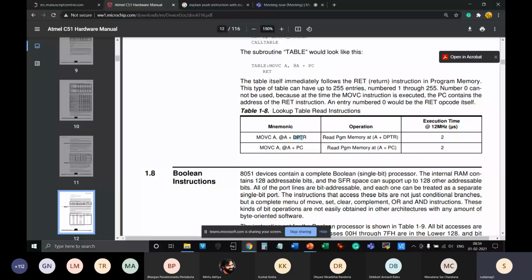Obviously your result should not overflow beyond 16-bit. Okay, that is another consideration here. The result of the addition of the DPTR value, a 16-bit value, plus the 8-bit value in the accumulator should not go beyond 16-bit. So the result of this addition must also be 16-bit, preferably, for accuracy. Basically, we have to make sure through our programming that the value does not go beyond that after addition.